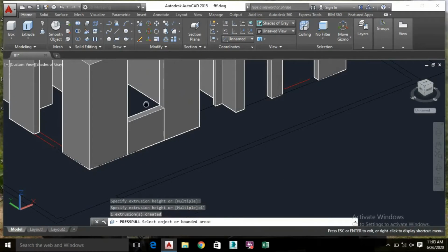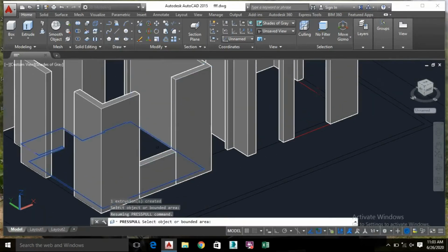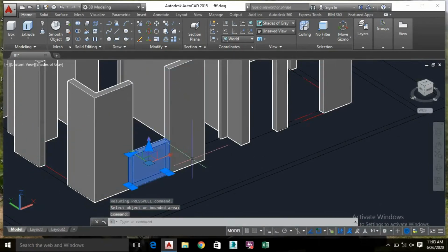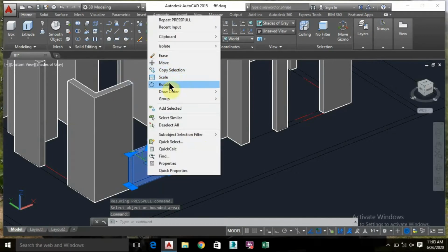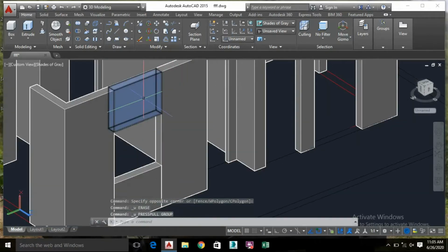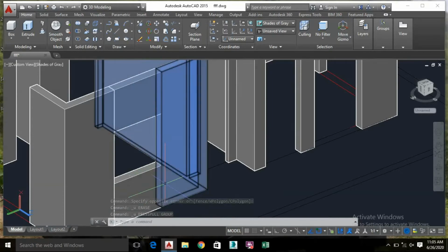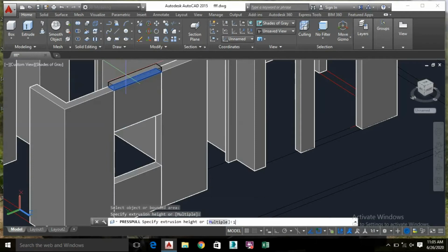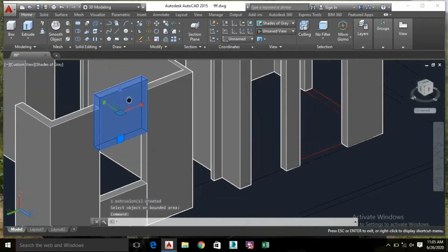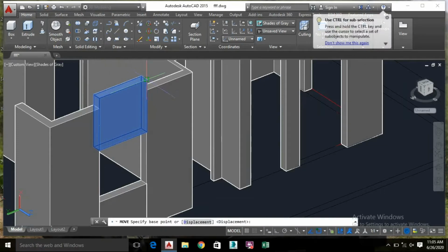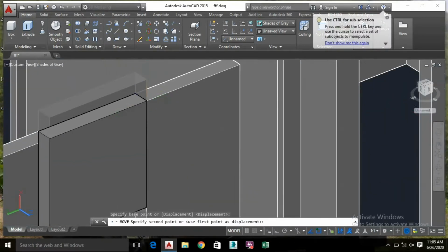Now I'll copy this same box at the top corner of this wall. Just select this, right click and copy this. Take this point as the reference point, press it and copy it here. Similarly I will make this type of section for all the walls of my house. Before that I have to increase its height by 1 foot more. So in total the window is 4 feet, and all the levels are 9 feet, so in total they will be 13 feet.